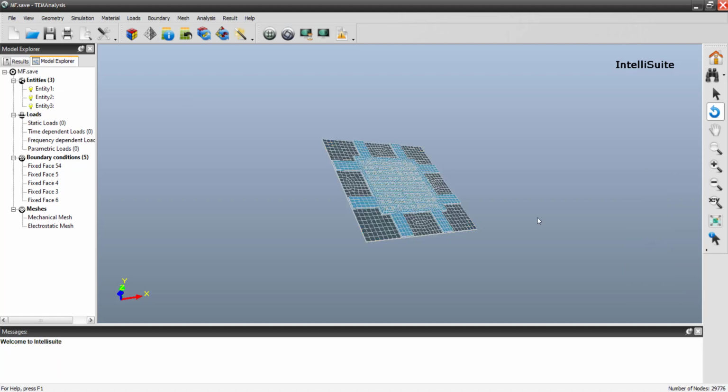So this simulation, whatever we have carried out, has given us the natural frequency value, and then it's given us the pull-in plots, and then the sensitivity analysis is carried out. In a microphone, or in any MEMS device, we always have something called squeezed film damping.